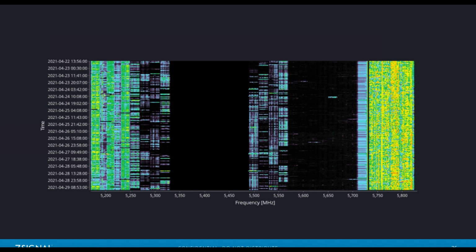Very, very disheartening to see this in the 5 gigahertz band, which is usually where we go when we see 2.4 gigahertz is a mess. Go to 5 gigahertz, it'll be nice and clean. And yet, for this unfortunate customer, the UNII-3 channels were just being dominated by that AV system day and night. Even when nobody was there doing karaoke, they were still transmitting away.